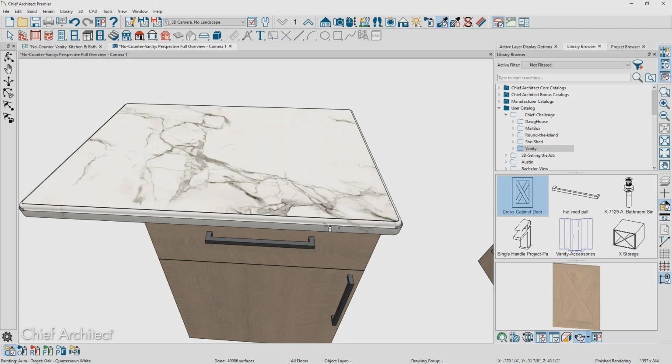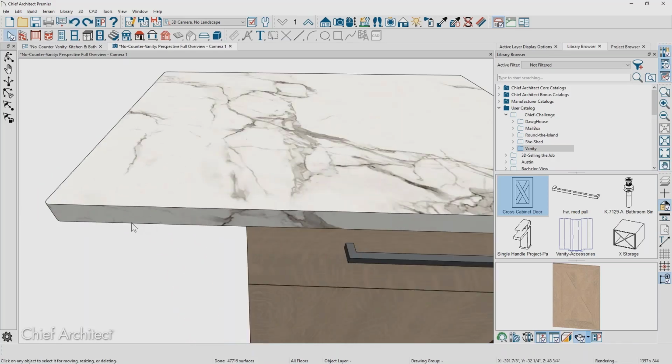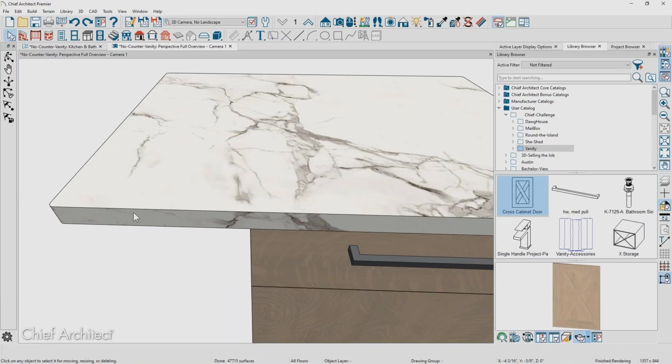John is asking, is there a way to softly curve the original custom countertop rather than adding a profile? Softly curve it, just the corner, at the top corner. Let me hit undo. So we want to softly curve this, similarly to how you're adding a fillet, but along the top edge. So it comes and curves slightly, like this? Yep. Okay. So that, I think, would be considered also an edge profile, and I'd probably just use a bull nose profile.